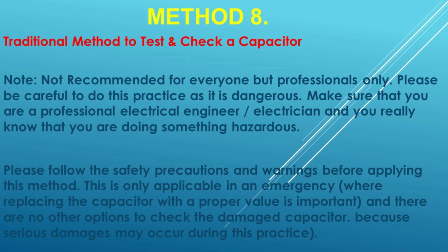Bulging bottom and lifted case of capacitor. If the produced gas pressure does not break the top vent of the capacitor during failure, it goes through the bottom and pushes the rubber, which makes the bottom bulge and lifts the case.